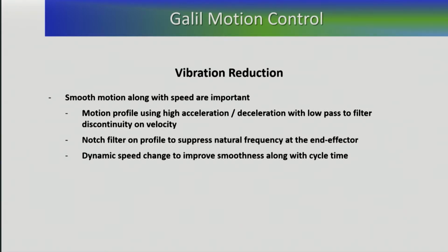For that, you take the approach of putting accelerometers. Put an accelerometer on the end effector, collect the data, and once you analyze that, you at least now have the information on what the resonance frequency is, and if there's one or multiple of them.